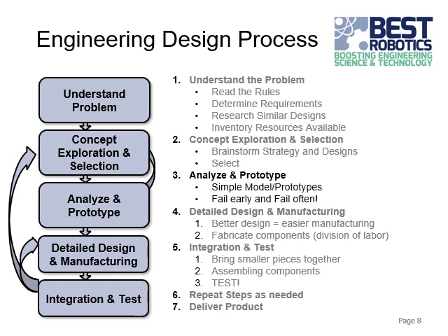And that brings us to the analyze and prototyping stage. So this is where you take those ideas that you've selected and you start prototyping them, modeling them. They can be physical models or digital models. Cardboard can be a really useful tool during this stage because you can cut it and glue it and tape it quickly, and just make very simple prototypes. A lot of times, they don't even function, they don't have motors or anything, but they're quick proofs of concept to show what it is that your idea is trying to do, and give an idea of, okay, is this actually feasible? Will it work?